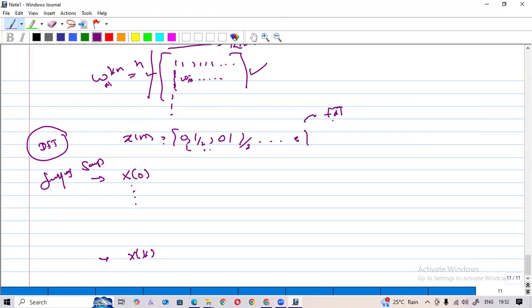So it will convert this time sample into frequency, omega. This omega will not be a discrete value, it will be continuous. So again, if you apply the direct Fourier transform, you will get a continuous time, continuous frequency spectrum, but not samples. But here you can get the frequency samples. So DFT is the sample version of FT.